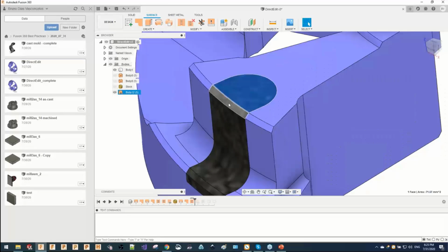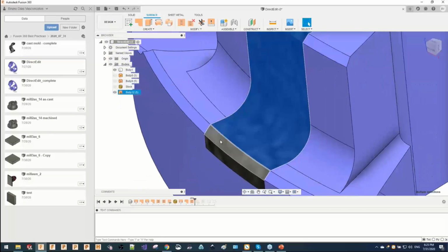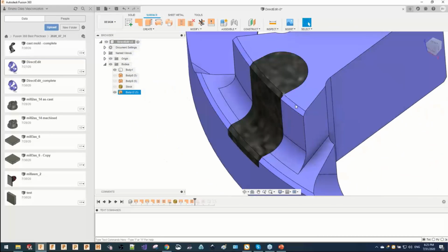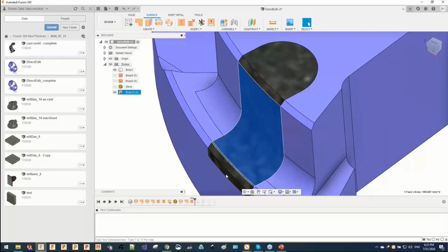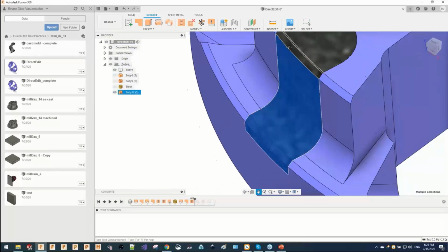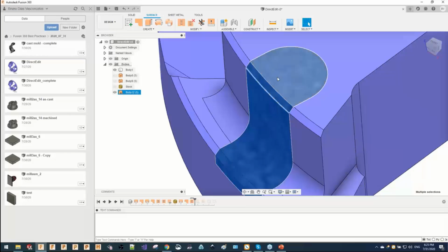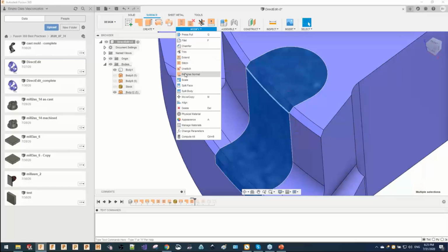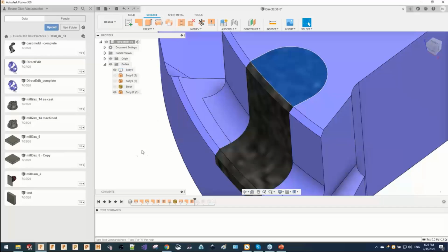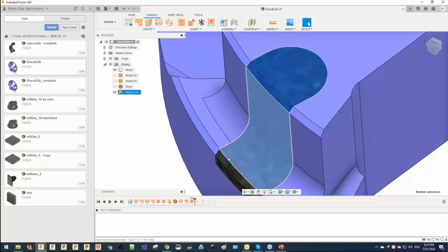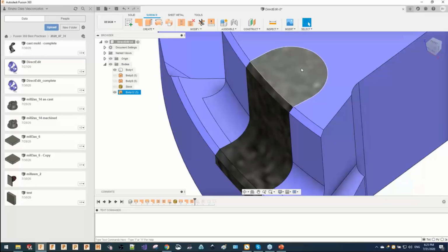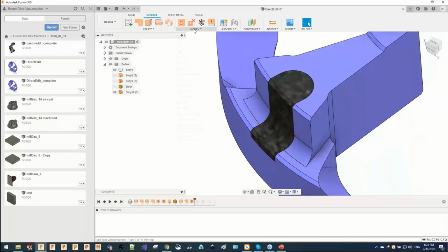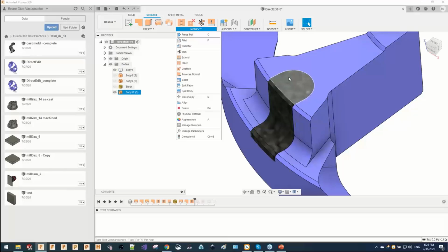And after we get this done, if you have a surface with a different style or a different color, that means the normal vector of the surface needs to be reversed. So if you go to Reverse Normal, it flips the normal direction of the body. This is why this surface has a different color from my model, because I need to reverse that surface. It is optional, okay?